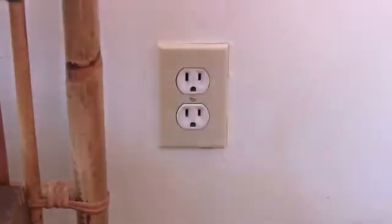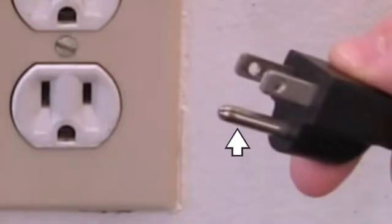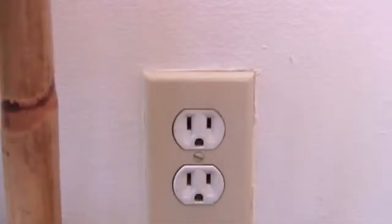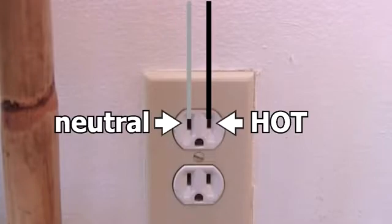In North America, this roundish hole is ground, and so the prong on a plug that goes in it is the ground prong. But to understand that ground hole and prong, we first have to understand the other two holes. In North America, they're called hot and neutral, and the wires are usually black and white. They're what carry the electricity that powers things.